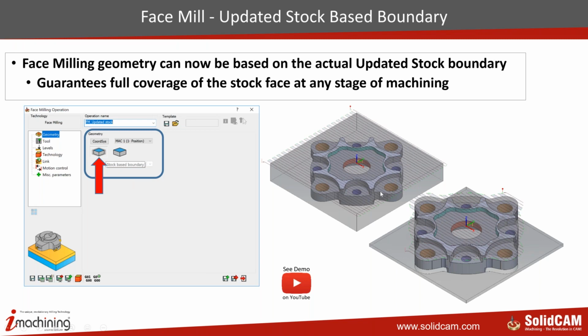In this example, if you see the first image, it has done the face milling for the rectangular stock that is defined initially. Suppose you have done the outside roughing. Immediately when you generate the face milling technology, the boundary will be updated with respect to the updated stock condition, and it does the face milling operation only within the stock boundary after the first outside roughing is done.